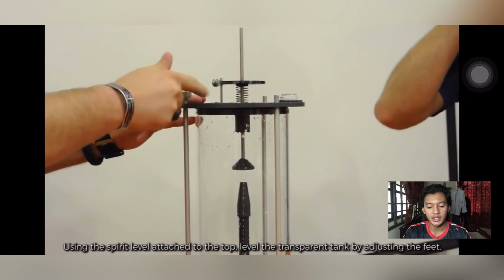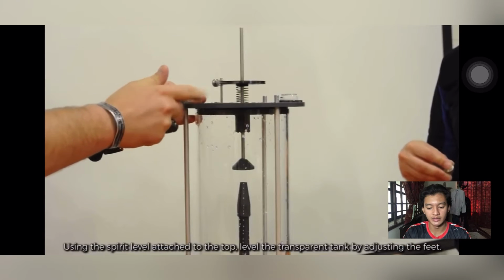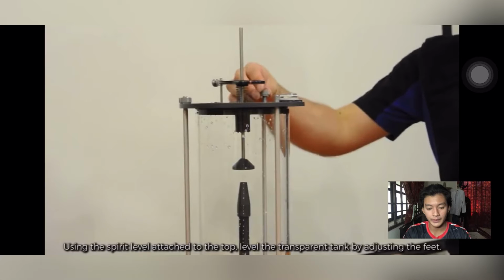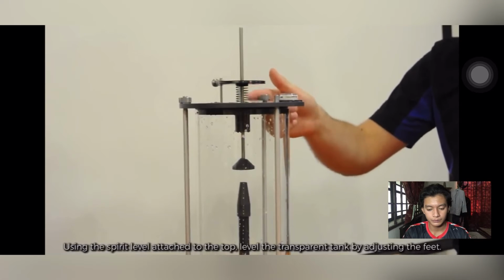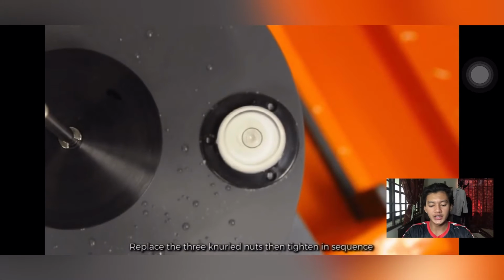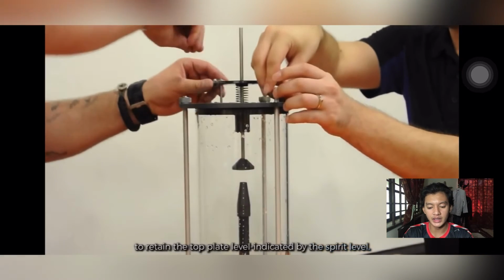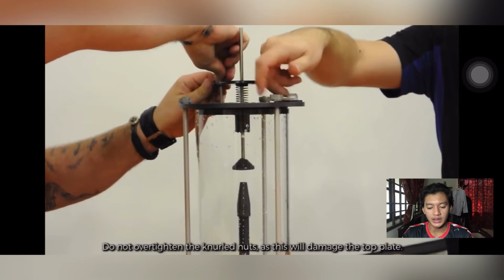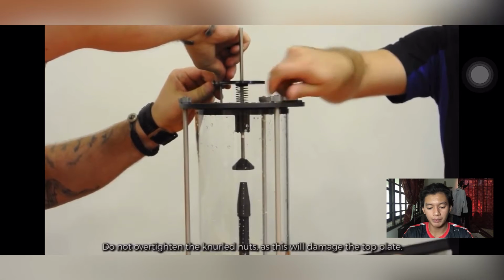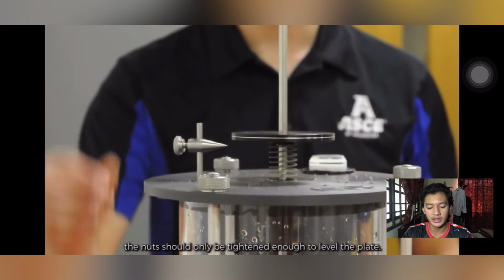Using the spirit level attached to the top plate, level the transparent tank by adjusting the feet. Place the 3 knuckle nuts, then tighten in sequence to retain the top plate level indicated by the spirit level. Do not over tighten the knuckle nuts as this will damage the top plate. The nuts should only be tightened enough to level the plate.